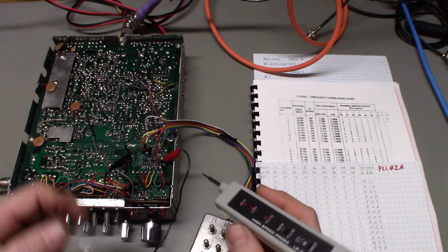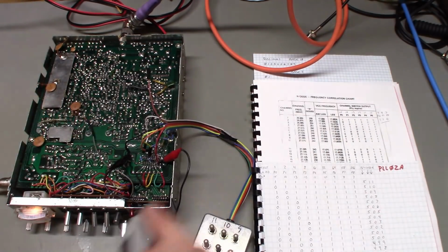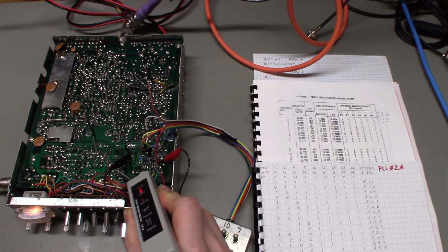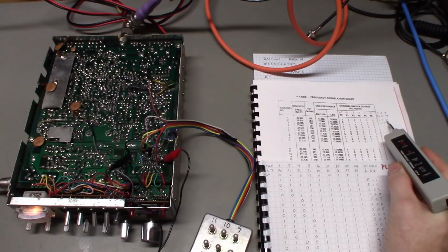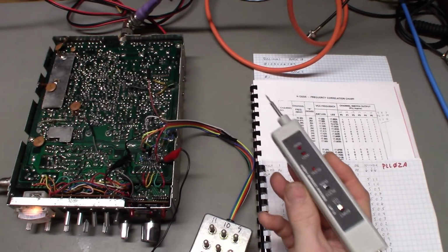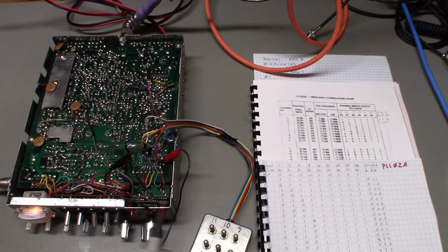And I'm never going to get, without getting my head down in here to see it. Well, no, actually I can just touch it over here. It's actually where it comes from. That tests as a low. That's actually pin 7, okay? But like I say, with the logic probe, you can make your own truth chart.